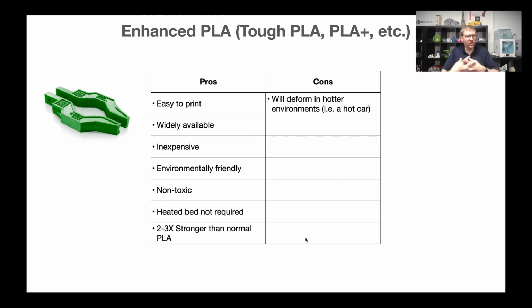Generally, the only property they don't have, that I have on the negative side here, is the temperature resistance, except for, as I mentioned, the high temperature PLA. So some nice options, and I definitely encourage you to look into the enhanced PLAs. They're really nice to work with, and they're generally not much more expensive than regular PLA. So these have become kind of my go-to for just general printing.